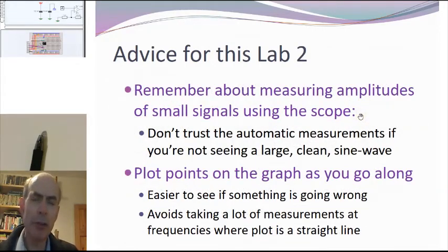Also, a reminder about measuring small amplitude signals on the scope. At high frequencies you are going to be trying to measure some very small amplitude sine waves. Switch on averaging, but make sure that the oscilloscope is stably triggered. It has a nice big noise-free waveform to trigger from.